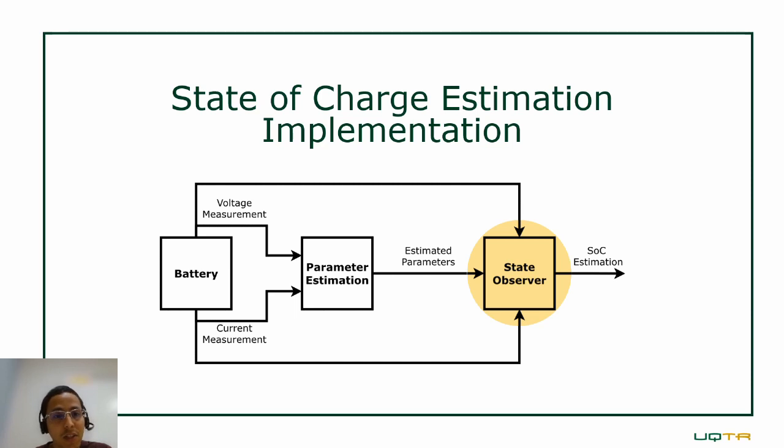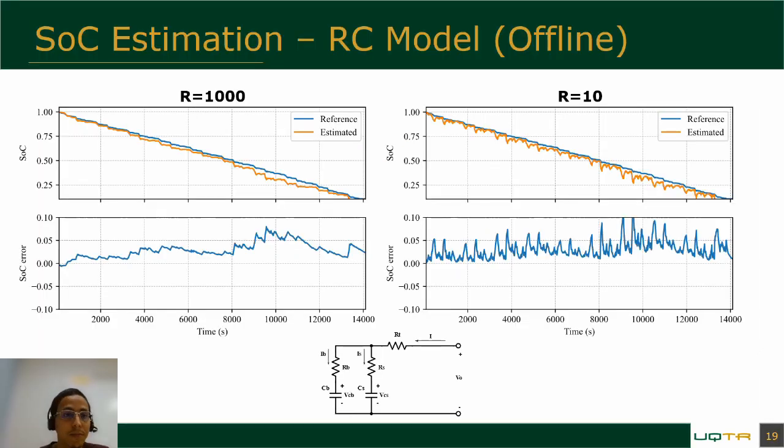The state of charge estimation was implemented using Kalman filters. Recently, several articles have shown promising results using equivalent circuit models in combination with Kalman filters. Using the bulk capacitor voltage as the battery open circuit voltage has provided good performance at high state of charge levels. However, the state of charge estimation performance at lower state of charge levels is not good.